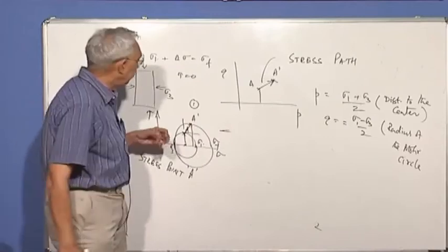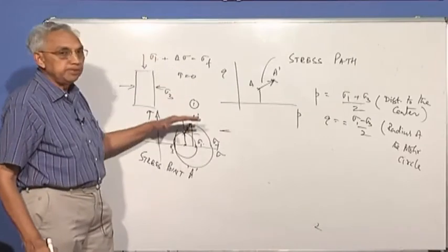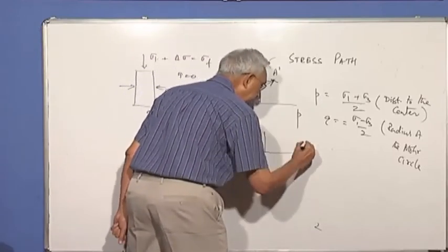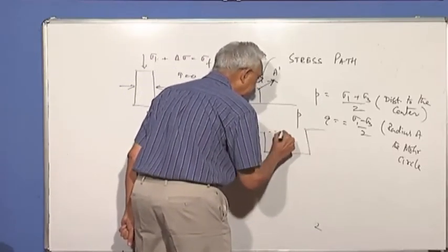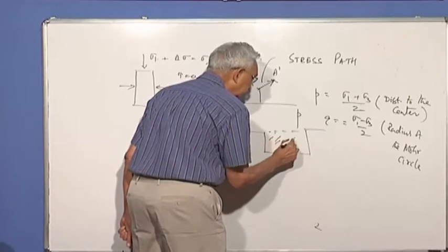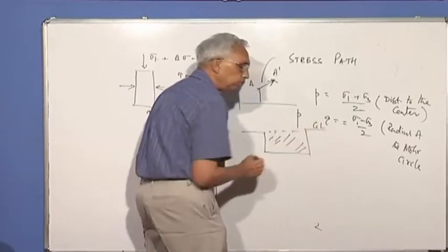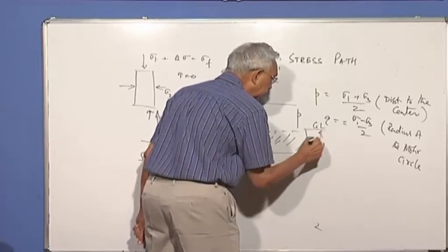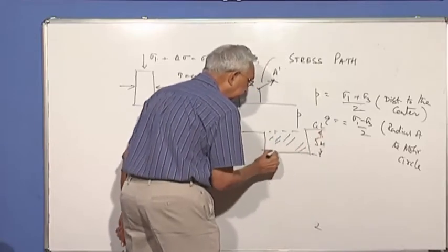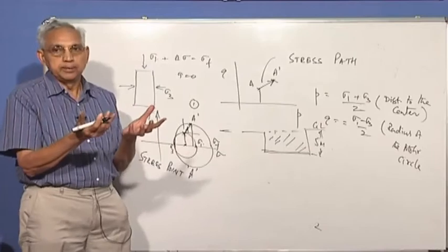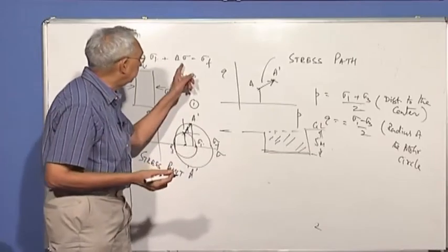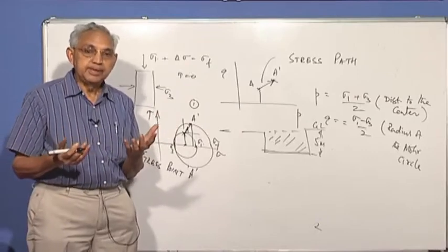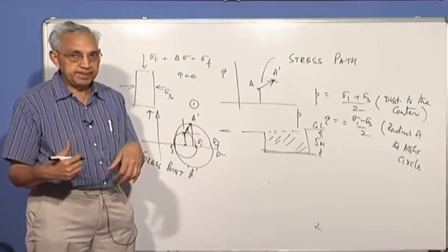When you construct a building, we have increased the load on the ground. Suppose instead of that, I have excavated. The ground was here, the original ground level. I have removed 5 meters of the soil. So what happened to the stress here? We have removed the load. So what is the direction now? Magnitude and direction: delta sigma becomes, instead of positive, negative.